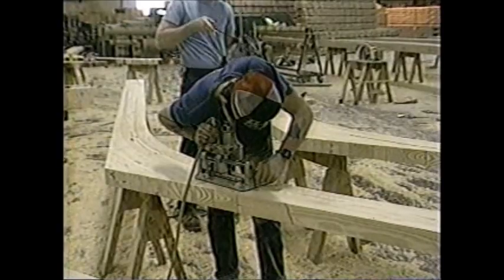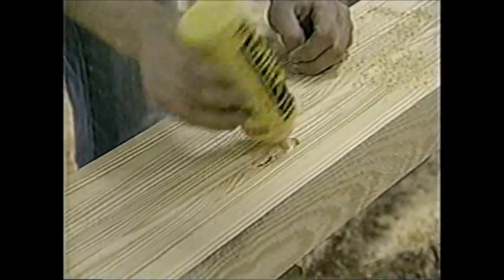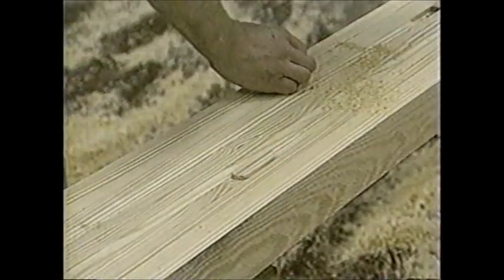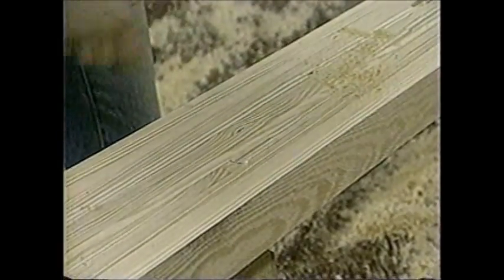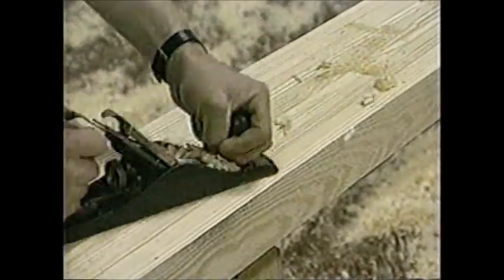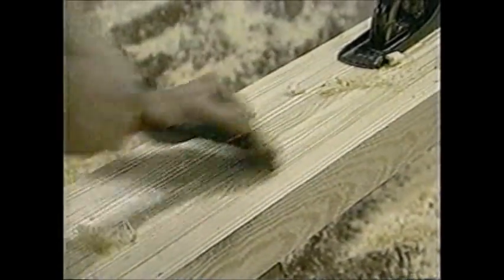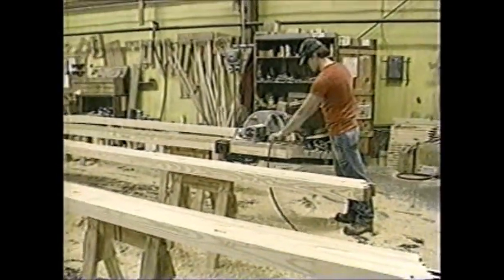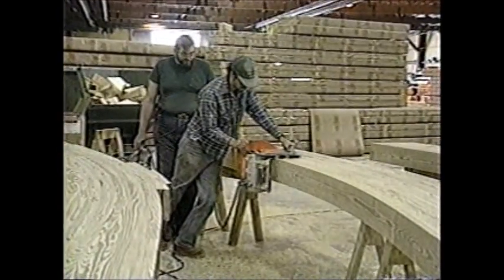Surface defects are removed by routing a standard router recess in the beam to specific depth. The recess is cleaned of sawdust, glue is applied, and a router plug is tapped into the recess. The surface is planed even with the beam surface, and a scraper is used to finish the patch. Curved surfaces are first sawed to the beam's pattern and then finished with a motorized hand surfacer.